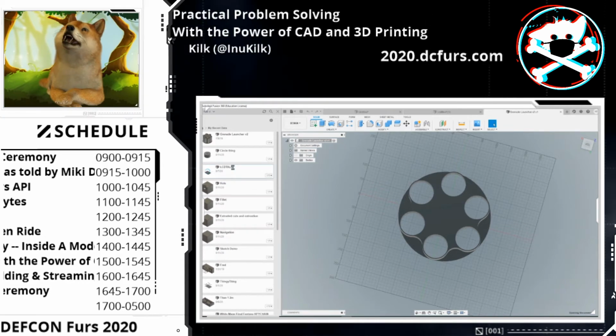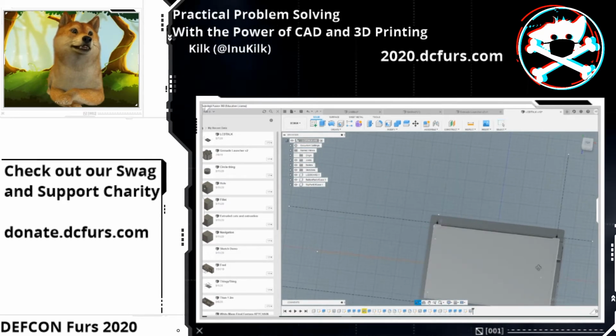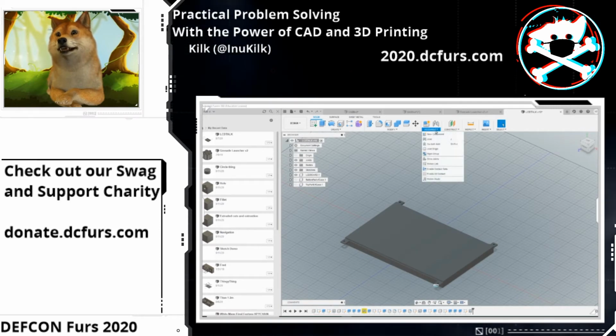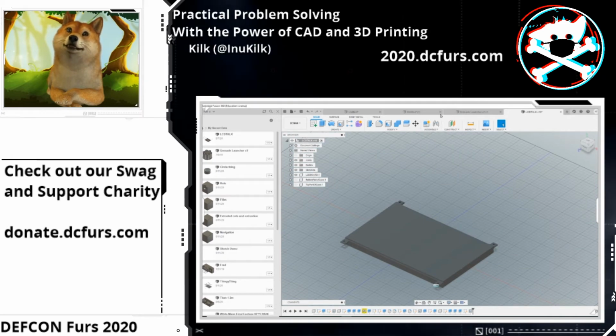The LCD. I should show this at least. This is what the whole talk was. I was doing this for the whole talk, and I barely showed this. There was something important that I wanted to show. When you're building a project, you usually want to build your sketches in a new component, so you can separate things, like if you have two halves of a case. If you don't separate these, when you're making the top and the bottom case, you're just going to have a huge timeline down here. There are a lot of operations that went down here, and this would all be combined, and it would be very hard to edit. So what you want to do is make a new component. I'll just show that right now.